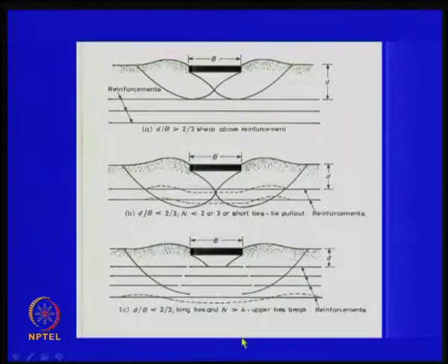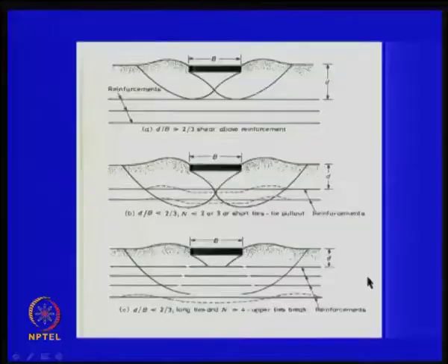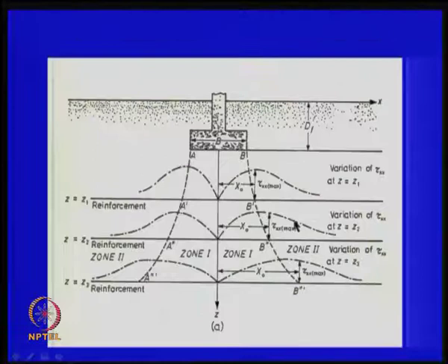Okay. Then there is another possibility, tension failure, like if the reinforcing element itself is not strong enough, definitely it can break, right. D by B is fine, and the length is also fine, but they all are very inferior elements. So, then there is no use, right. And so, we should see that the design should be such that all these three mechanisms are avoided. If somebody can come out with another mechanism, nice, you can always think of these mechanisms and see that they are all avoided. Okay. They are all simple assumptions, and what he did in the analytical work, how did he do that?